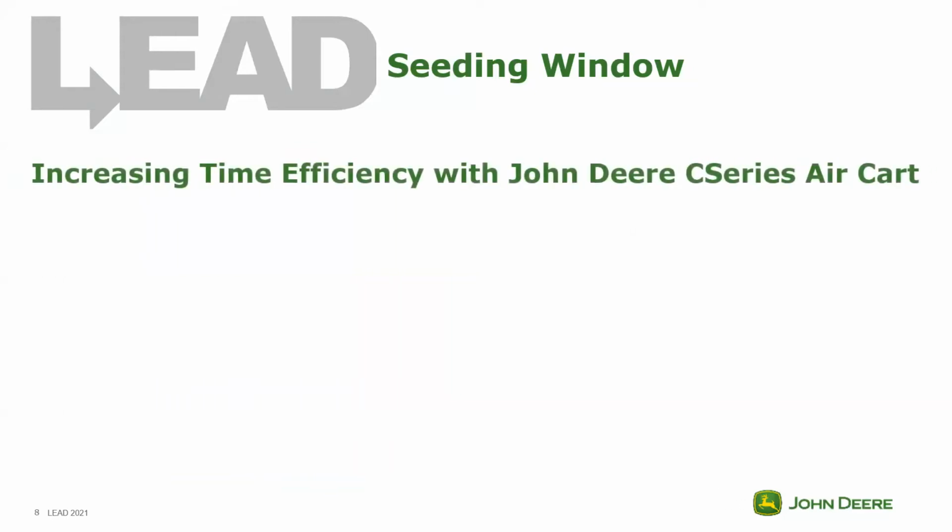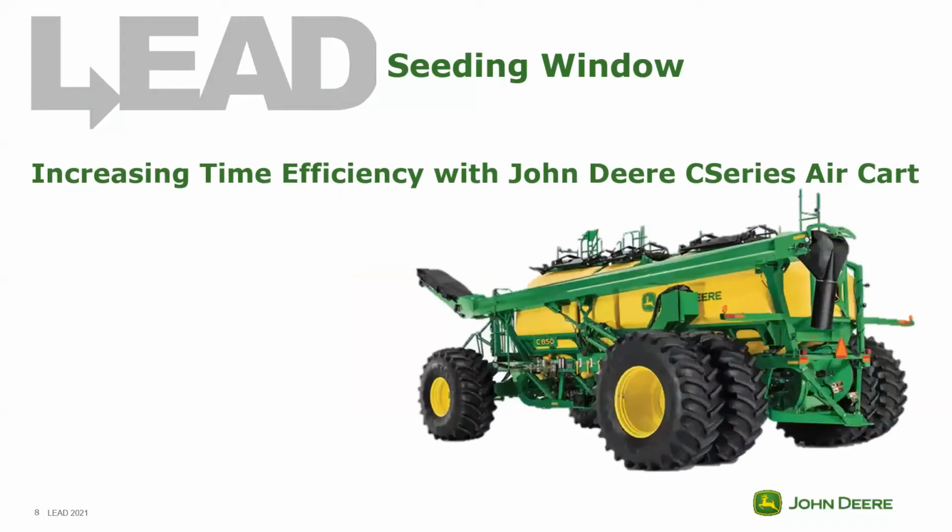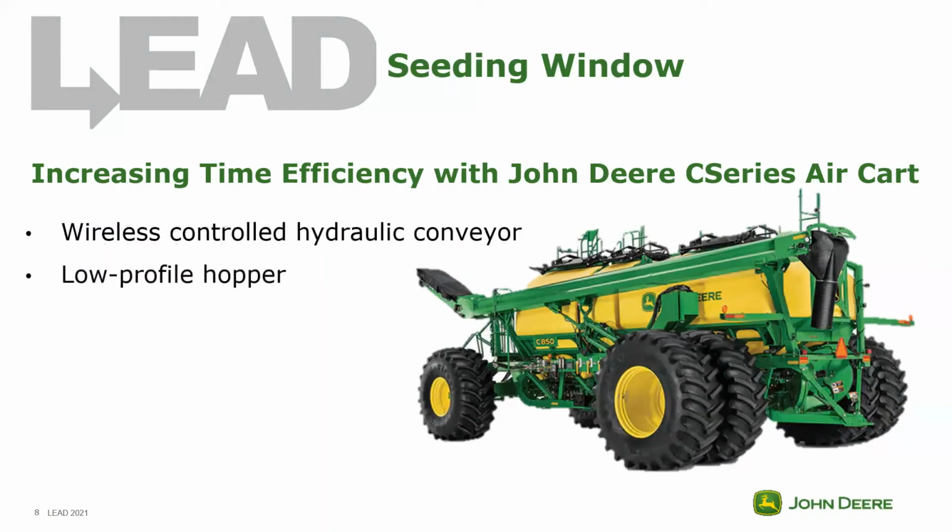With time being of the essence at seeding time, it is very important to look at your equipment choice for efficiency opportunities. With a large 850 bushel capacity, the C850 air cart can accurately cover 170 acres per fill, easily covering an entire quarter section. The wireless controlled hydraulic conveyance with low profile hopper allows for 100 bushels per minute. The 16-inch belt with 12-inch tube can fill the entire unit in as quickly as 20 minutes. It fills the entire tank from one spot with a 5 pivot point control arm.